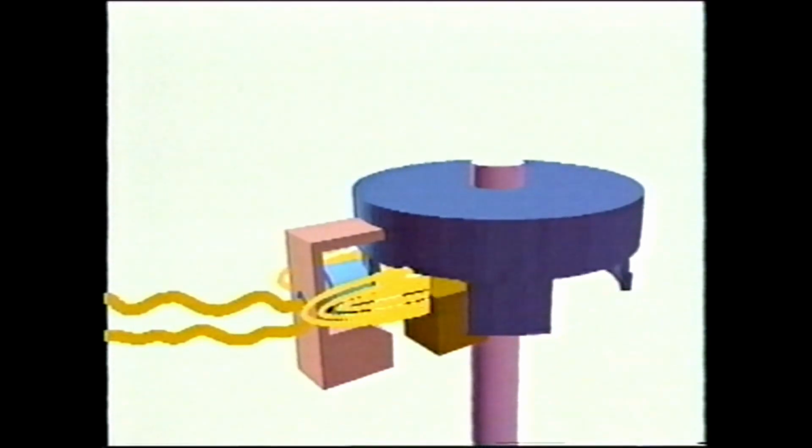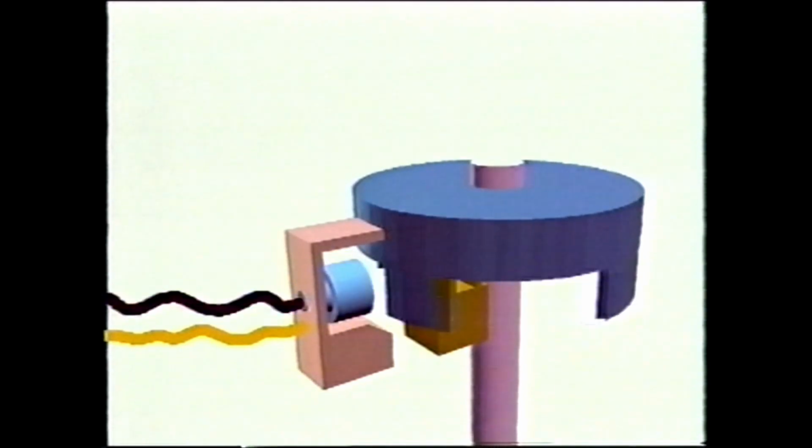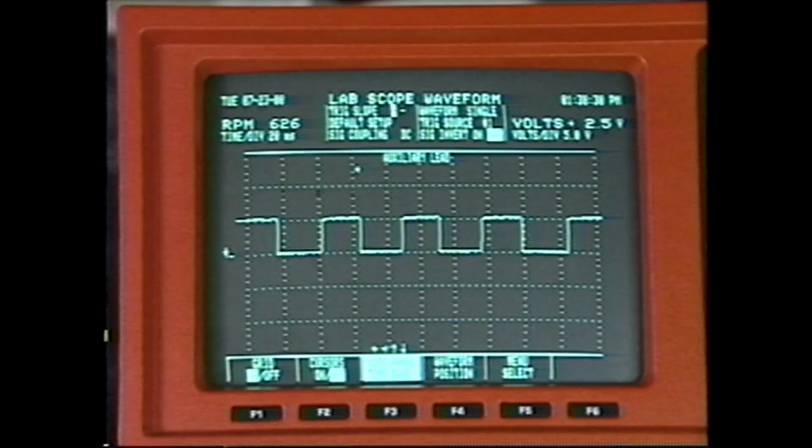As a shutter blade enters the gap between the magnet and Hall element, a magnetic shunt is created, the voltage collapses, and the switch turns off. The abrupt on-off changes in the voltage level are displayed as a square waveform. The rate of the wheel's rotation doesn't affect the level of voltage where the switch turns on or off, so the voltage does not increase with increases in engine speed.